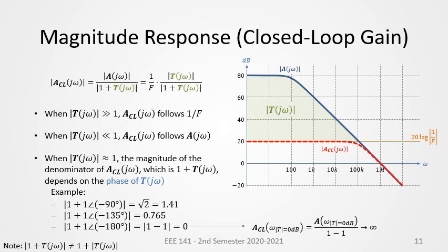So if you recall, the magnitude response or the frequency response is evaluated at S is equal to j omega, and if the pole now lies at the imaginary axis of the complex plane, then the infinite response at the exact pole locations will now appear clearly in our frequency response.